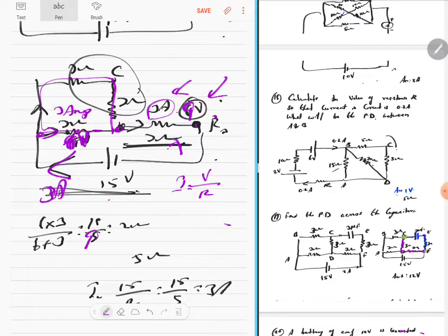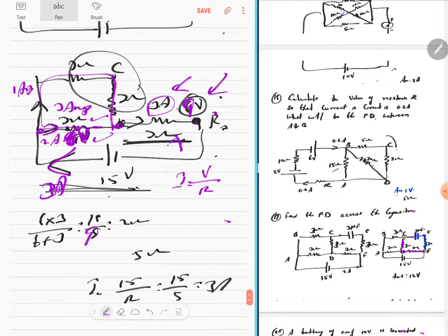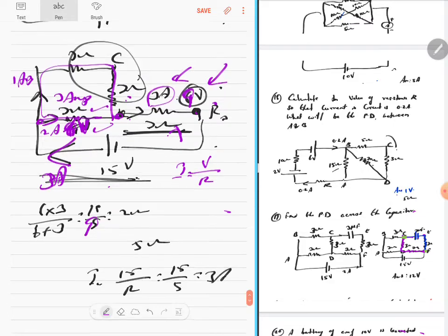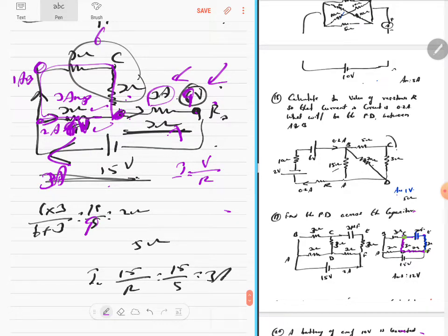So you know voltage, you know the resistance, 6 by 3 is 2 amps. So therefore here 1 amp will flow. So 1 amp flows through here. These are series. So then 1 into 3 is 3 volts, and 1 into 3 is 3 volts. 3 plus 3, 6 volts is the potential difference between this and this. Obviously they are parallel, so it will be 6 volts only.